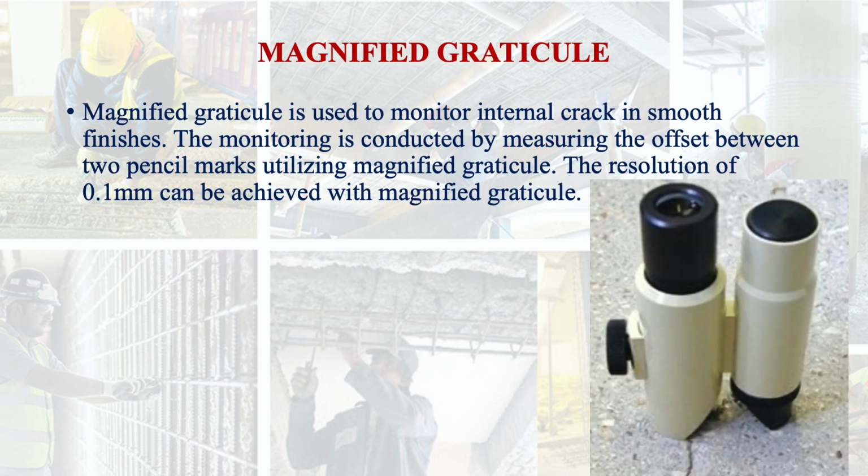Magnified graticule. Magnified graticule is used to monitor internal cracks in smooth finishes. The monitoring is conducted by measuring the offset between two pencil marks utilizing the magnified graticule.